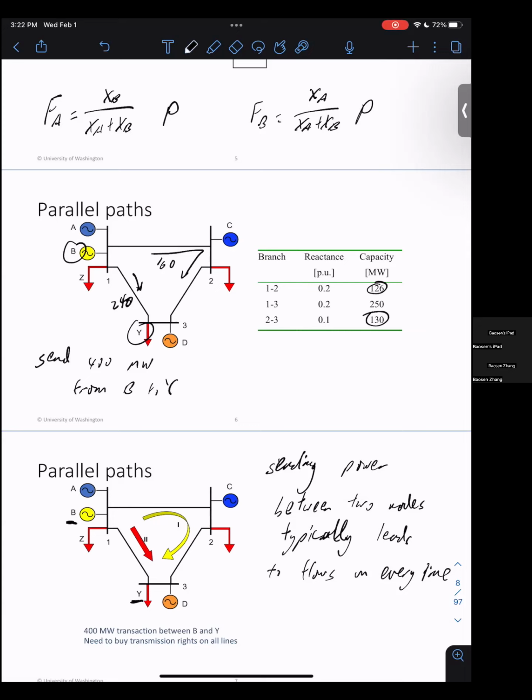Right. Okay. Good. So the question is, if you increase capacity, will you increase reactance? Most likely no. When you increase capacity, reactance goes down. The most typical case is you build a parallel line. You just build some line in parallel to it. When things are in parallel, the total reactance goes down. Right, it's the reciprocal of the sum of reciprocals.